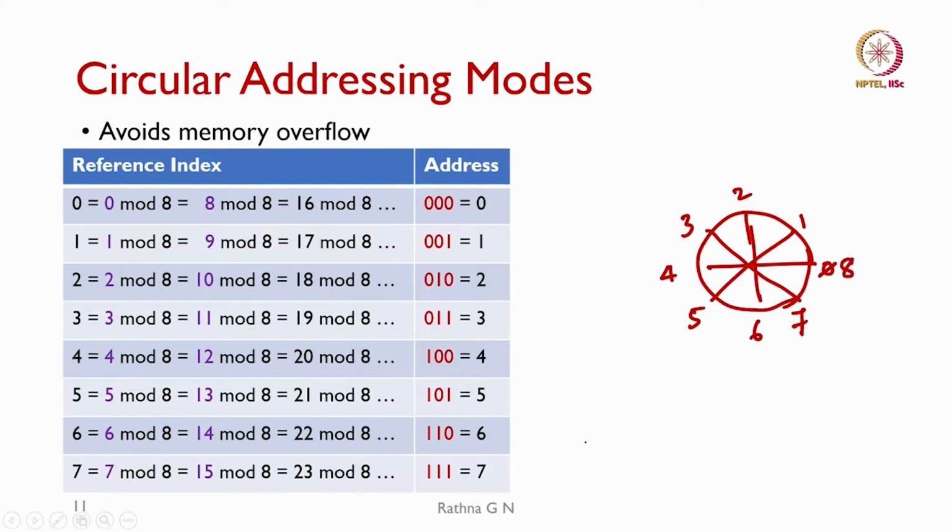So, what is going to happen to the 9th sample? We will be overwriting on location 1. This is what is shown with the mod values, how we will be storing it in only the 7 locations. So, why do we need the circular addressing?